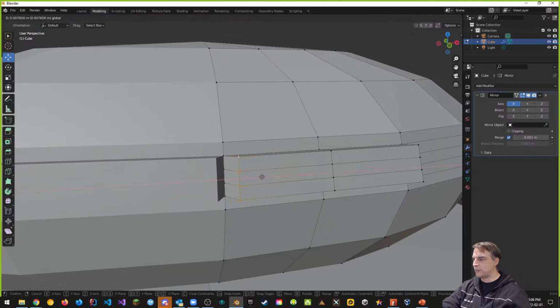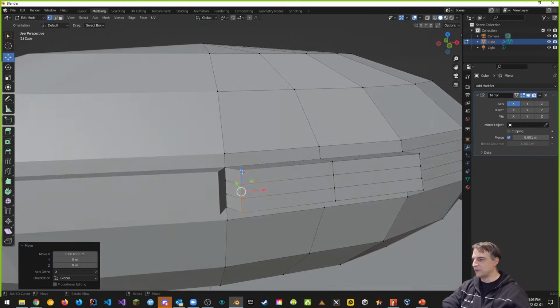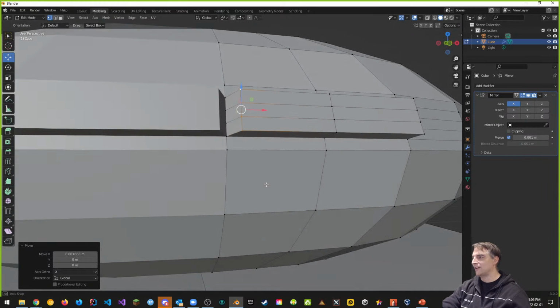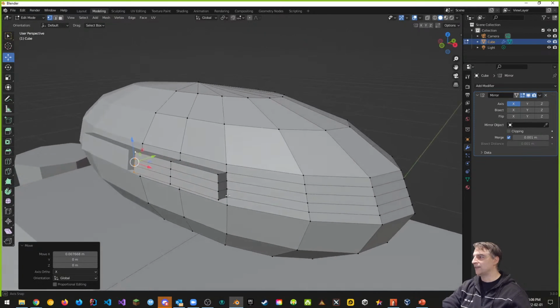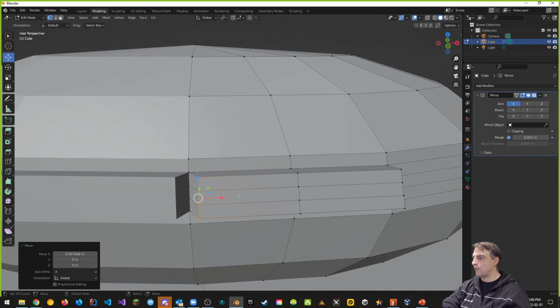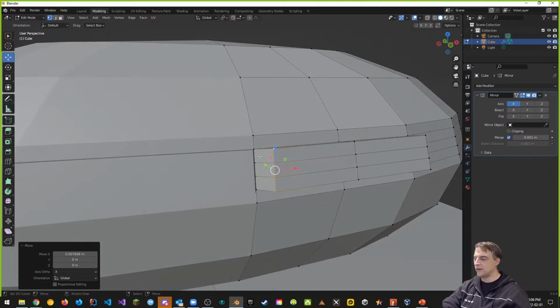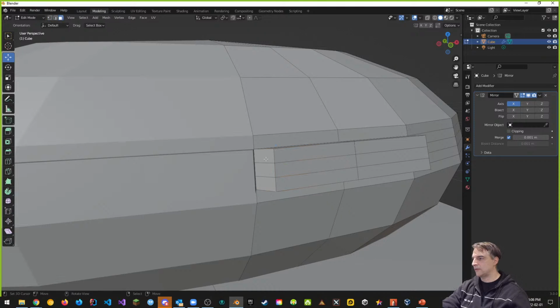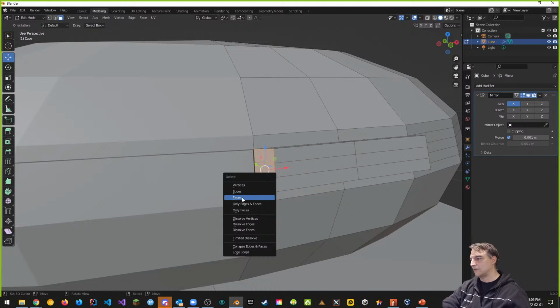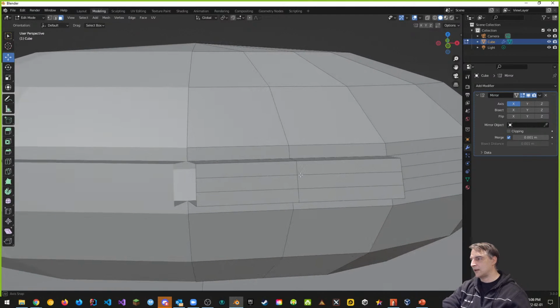And I want to use this just to pull it open a little bit. Notice that I'm almost like doing open heart surgery, open eye surgery here. So I can do this. I can have 2 eyes, one on one side, one on the other. But one thing I know is that I'm not going to need these faces inside of here. Let's get rid of them. So again, Control into face select mode, select these faces, press the delete key, which will allow you to remove faces. So the faces are gone.